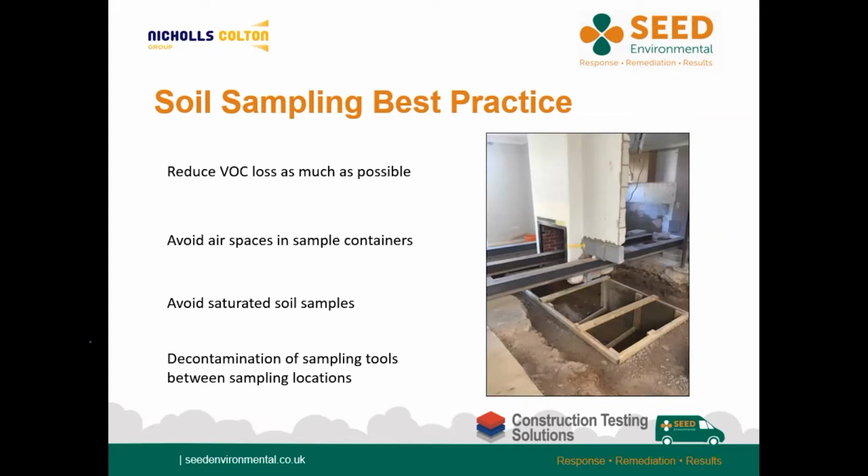When sampling from an open excavation, it is important to ensure that the facing material is removed before you collect a soil sample. This material has been exposed to the atmosphere, and any VOCs may have evaporated or diffused from the soil or may have been leached out by rainfall. When filling sample containers, ensure that all headspaces are removed, as these would allow volatiles to partition out of the samples and be lost prior to laboratory analysis.